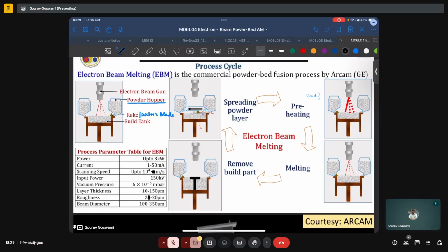Electrons, on the other hand, are charged particles, and if by some focusing means, say electrostatic focusing or magnetic focusing, we are able to confine a flux of electrons into a region which keeps getting smaller, it will not be able to go beyond a certain extent, which in this case is typically 100 micrometers, because after a point these electrons will come very close together, and because of their charge will start repelling each other very strongly, and physically it will not be possible to confine them any further.